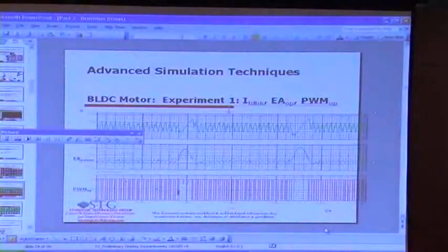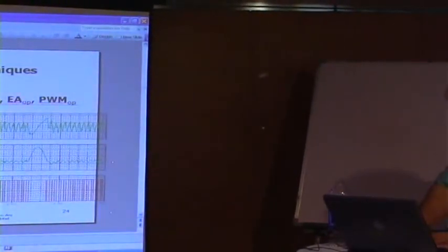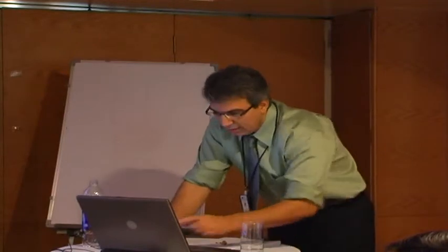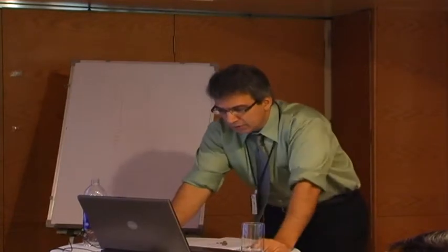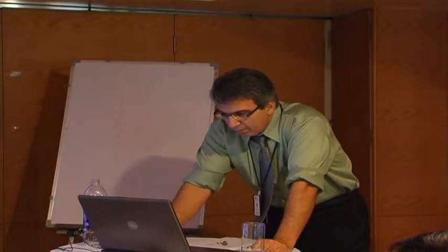Well, there are small glitches on the PWM signal that I could not see. Those are convergence issues. Yeah, I think here we had a convergence problem. The system recovered, but we didn't have a convergence issue here. But we have a duty cycle block, right? We are limiting the duty cycle to 1% to 99%.